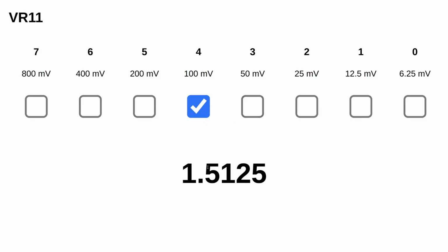Usually the assumption is you're not going to run it at 1.5 volts by accident without paying attention. At the same point, this is a lot safer than a feedback mod in the sense that you can't accidentally set it way too high. So for instance, if you don't put a limiting resistor on your feedback mod on some controllers, you can easily have it go to 3 volts by accident, especially if you turn your pot the wrong way and you started up the card with it set to max voltage. Maybe you sent 12 volts through your processor right away.